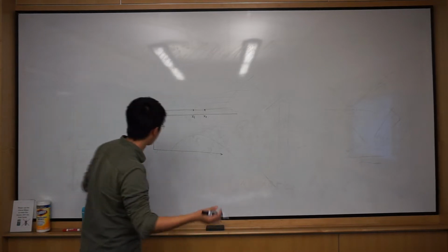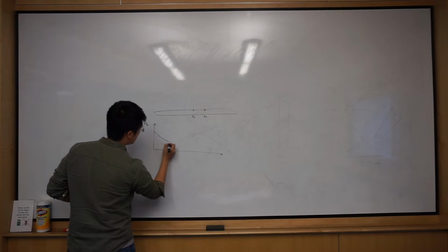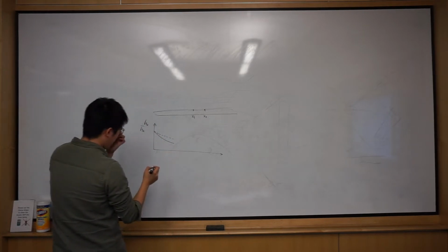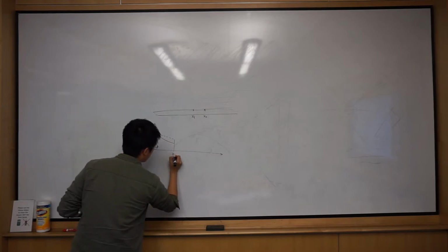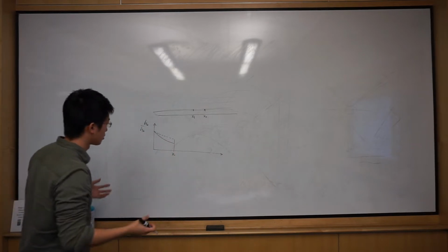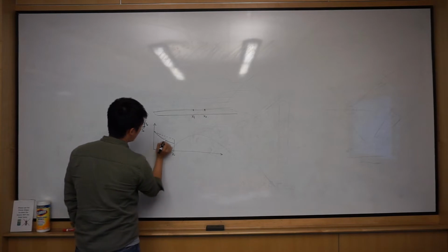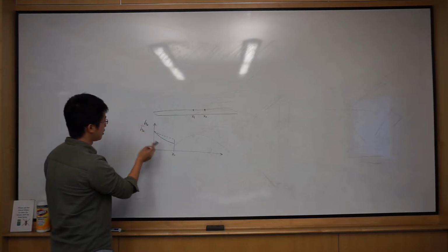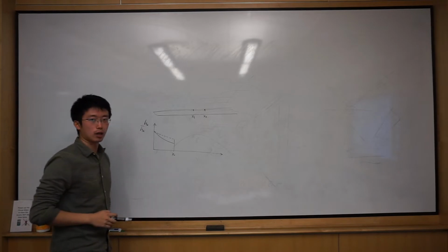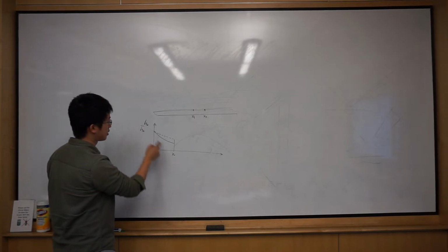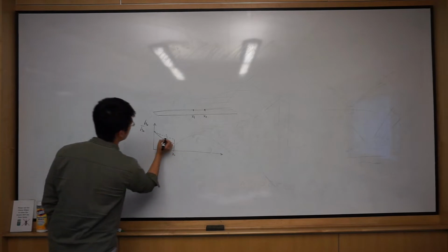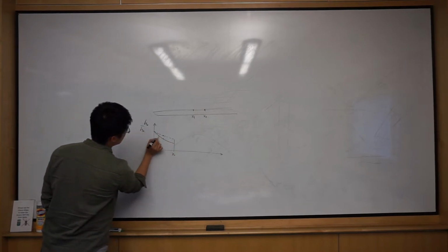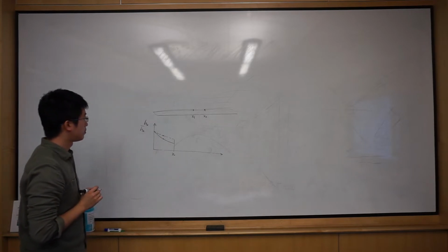For laminar, this is the critical Reynolds number position. The average stands on top of the local coefficient because the local one keeps decreasing and the other is an average, right? So at this point, it's basically averaging from here to here, right?